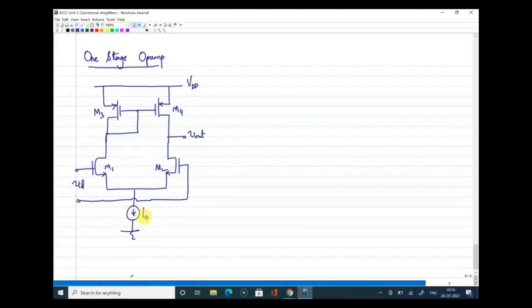So what you are seeing on screen now is a differential amplifier, but this is also considered as an operational amplifier, as I think the same thing was discussed some other day. If this is a high gain differential amplifier, definitely this can also be considered as an op-amp. Now, looking at the circuit, can I know what is the gain of this circuit?